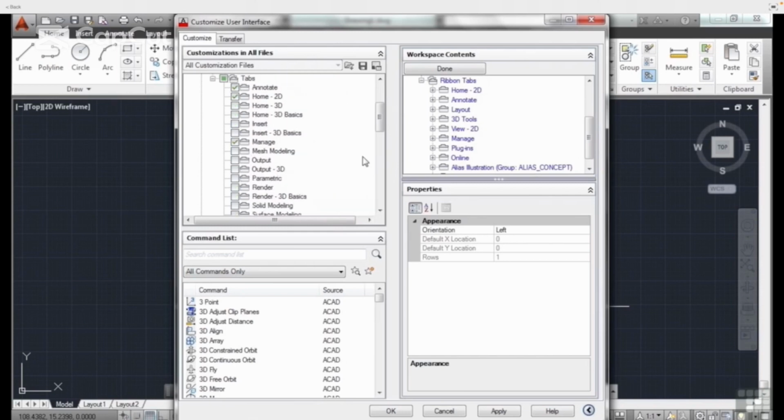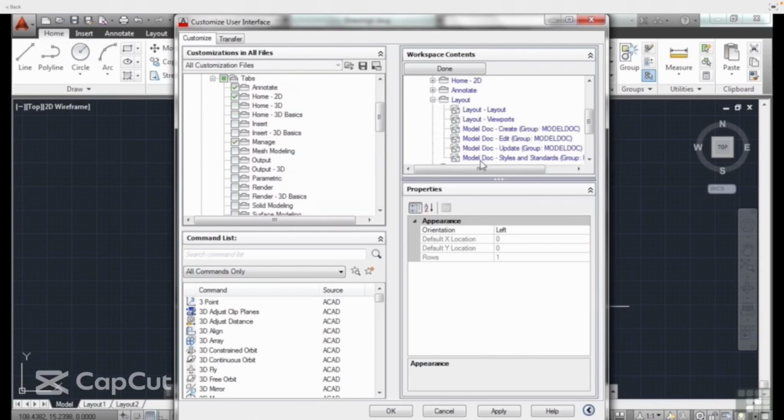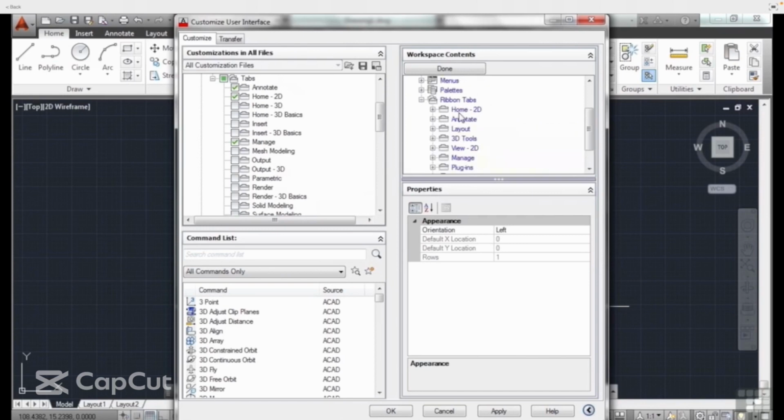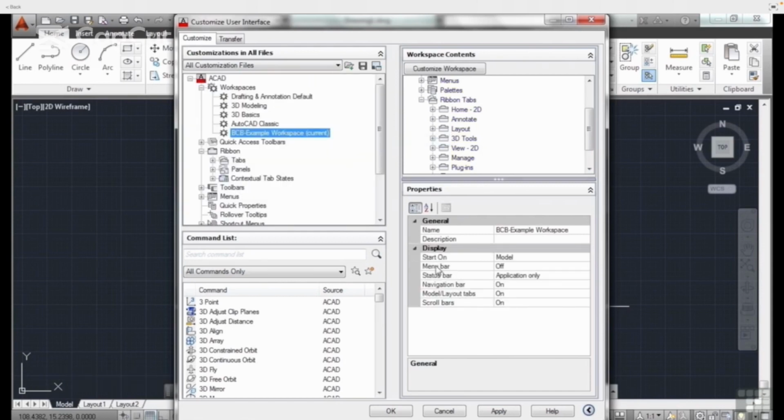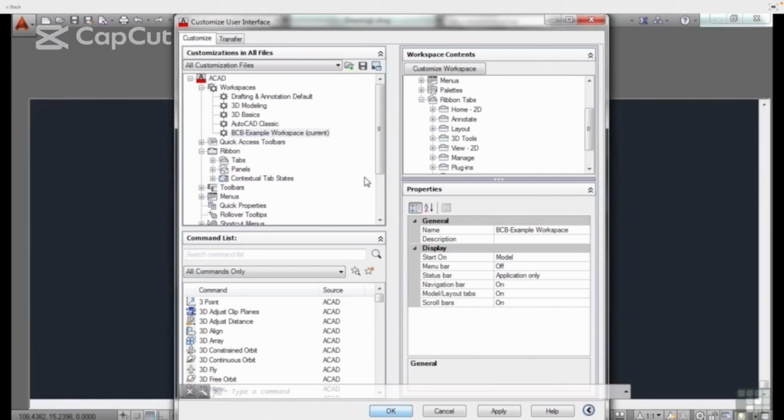and we're good. Now I can even come over here and I can see and verify, yes, it has what I want, and we're good to go. I can go and make these changes, all that I need to. So basically, to organize this, all I need to do is just turn these things on and off as appropriate or as I want. Then when I'm finished, I right-click on my workspace, hit exit, and I'm good to go. Hit OK, and then AutoCAD will update my workspace accordingly.